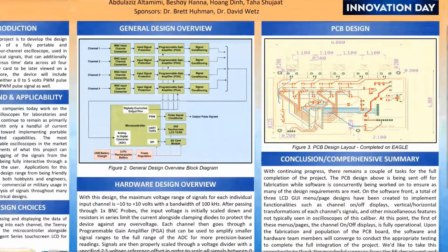As far as the printed circuit board and assembly are concerned, here's a complete PCB design ready to be milled. The dimensions are 6 by 4.3 inches. 2 layers are used for traces and polygons. The top layer is used for placing components and ground planes. The bottom layer is used for a 5-volt plane to power the entire system. Analog and digital grounds are separated through a 0-ohm resistor to minimize possible noise resulting from digital components.